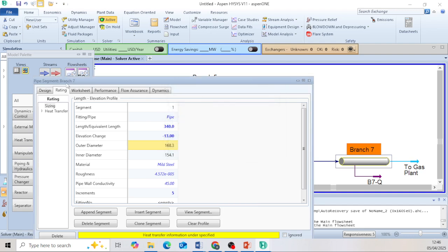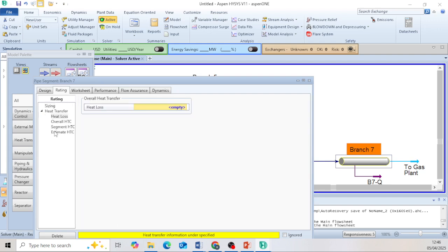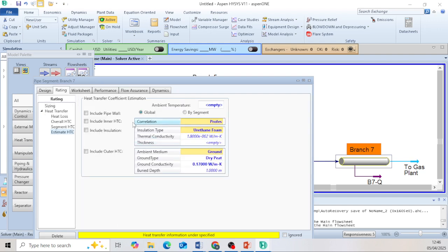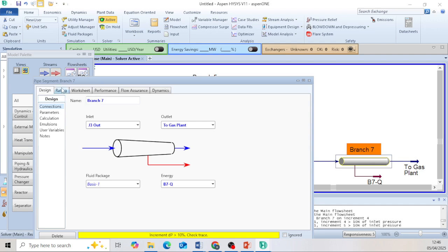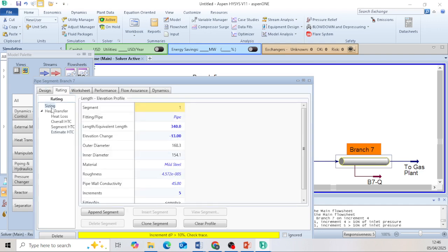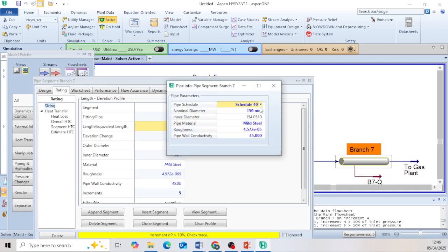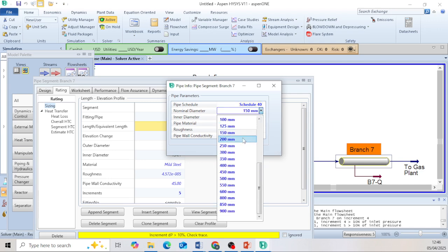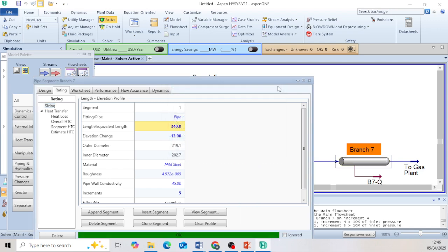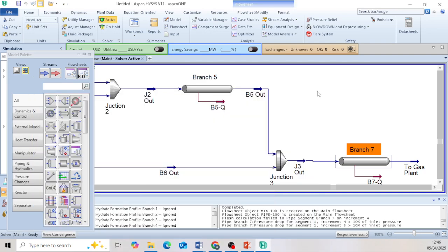All right, and then specify the estimates inside, and the temperature is fine. All right, so just need to increase the pipe segments for the last one. And then the system should converge. Let's do that. Okay, let's increase this, and voila, the system is converged.